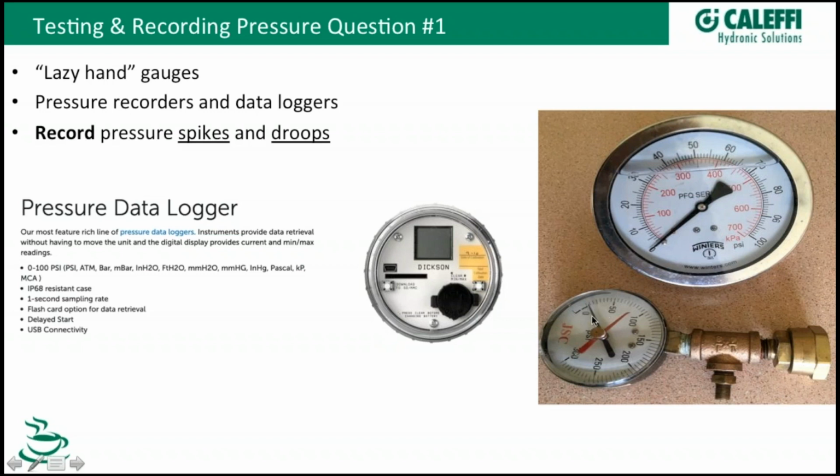So it's got the regular pressure gauge needle right here, the black hand, and then this red one. You turn it, you can see the little thumb screw on it, turn it down against that one. Let's say this goes up to 50 pounds of pressure and you get a pressure spike. Obviously it's going to move the red needle, and the red needle is going to capture that high pressure spike. So if you go back the next day or a week later and say, gosh, it went up to 200 pounds, well, you've got a water hammer, you've got something going on. Or if it goes up there and stays there, it could be your pressure reducing valve is leaking through. So this is a good way to capture information when you can't be there to catch it in the act, so to speak.